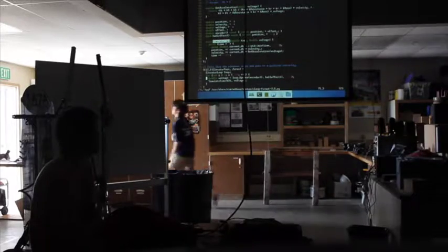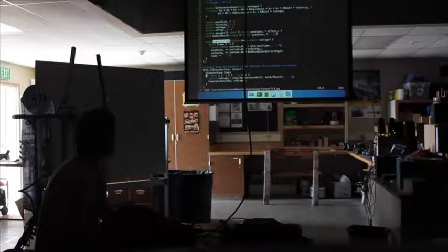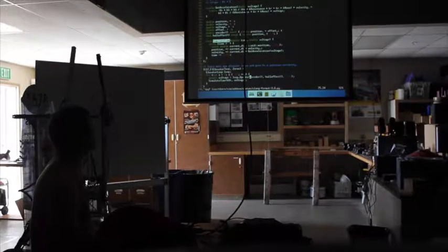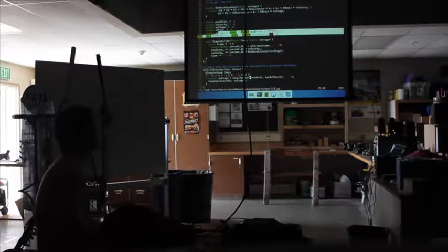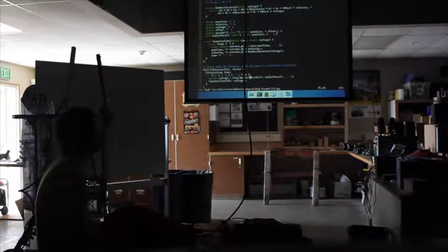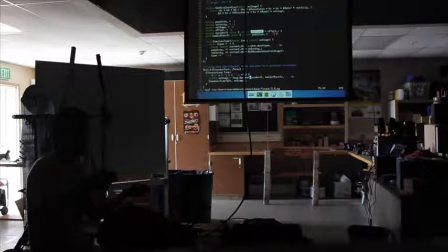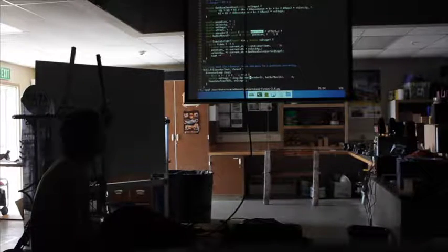So let's walk through a little more what's going on here. So encoder, we've got written some functions up here. So we've got our encoder value is computed as the absolute position plus some offset. So if you don't start the encoder where it's perfectly at 0, you start it off somewhere, you're going to get a different value for the encoder than your actual position.